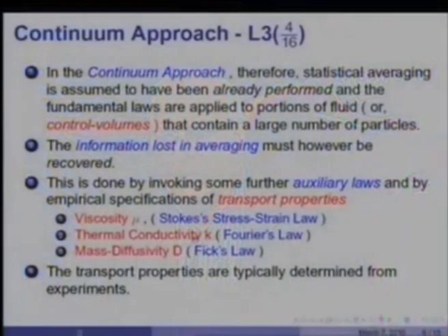The three auxiliary laws that are normally invoked are, firstly, Stokes' stress and rate of strain law, which defines the fluid viscosity mu. Fourier's law of heat conduction, which is familiar to you, defines the thermal conductivity K, and Fick's law of mass diffusion defines the mass diffusivity.